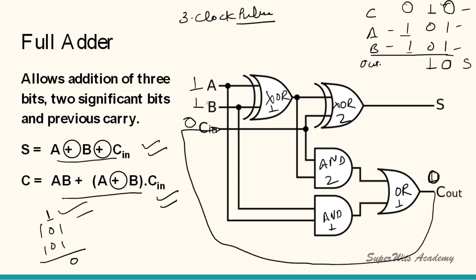So both the inputs are 1, or high, on the XOR 1, so it is going to give me 0, and for the AND gate, because both the inputs are 1, the output will be high. In the second set of half adders, Cin is 0, so when both the inputs to the XOR gate are 0, it becomes 0, right? And for the AND gate again it's 0 and 0, the output will be 0.